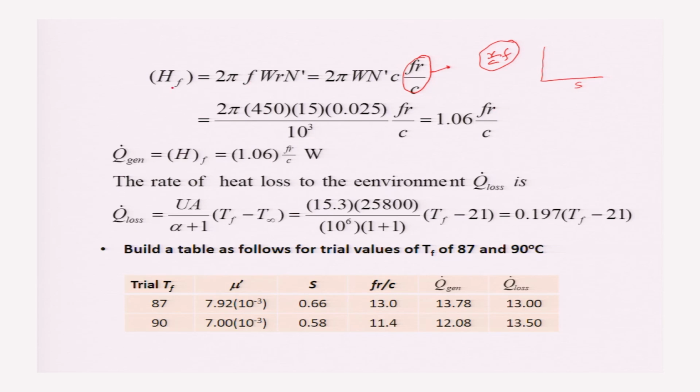The heat generation, this frictional power, will be given by 2 pi f W R and N. This f W R is actually the frictional torque.